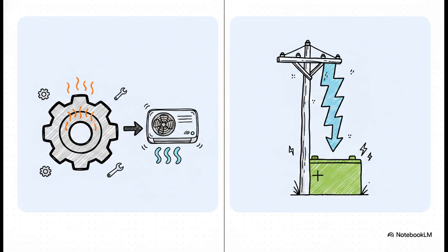On the flip side, we have volt-amps or VA. This is the apparent power. It's what the utility actually delivers to the room and what your uninterruptible power supply must be sized to handle. The electrical engineer needs VA. Listen, if you size your UPS using only watts, you are going to undersize it. Guaranteed. No way around it.